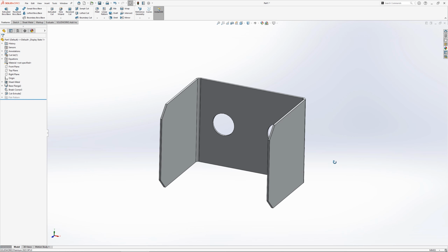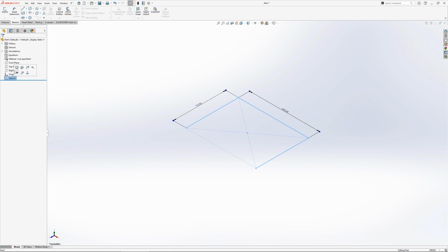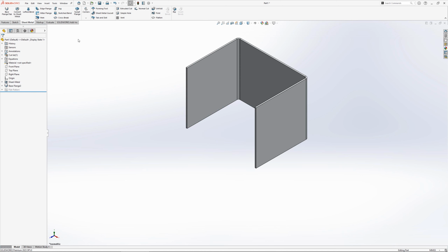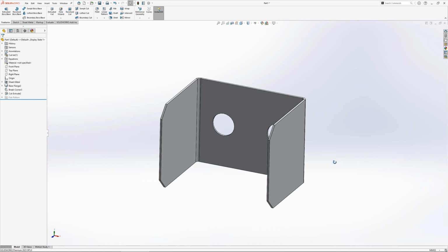When modelling in SolidWorks, it's important to choose the best profile to start with, and the same applies when using sheet metal tools. Take a look at this example. Using the base flange method, there are two approaches that could be used to model the part. An open sketch profile could be drawn, with the sheet metal thickness being offset about the sketch and the length of the part extruded. This would leave the detail of the chamfer and the holes to be added as separate features.